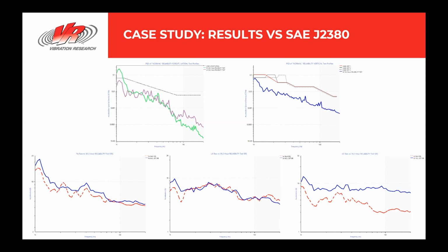So to summarize, the key to success for automotive suppliers is to design components that meet reliability targets, keep warranty costs low, while at the same time achieve low production costs. Traditionally, automotive components are tested using generic specifications based on historic damage profiles with little connection to the vehicle that the component will be used on. The result is that the component may be over-designed for some types of vibrations while remaining vulnerable to others.